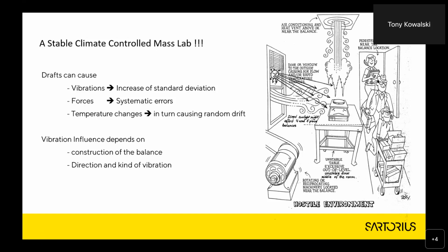However, with low frequencies, so again, if the floor is bouncing, or you have a motor, or you have a drift, a low frequency effect is indistinguishable from you adding a small amount to the weighing pan. The digital filter cannot differentiate between a low frequency vibration and a small addition to the weighing pan, and therefore these have the biggest influence.